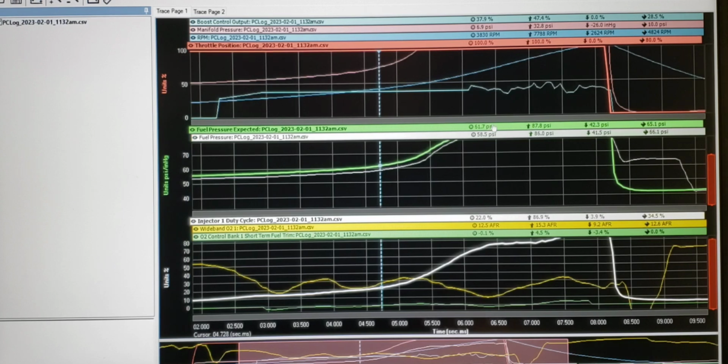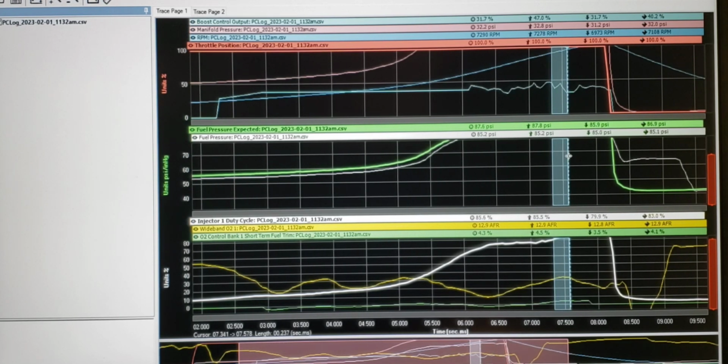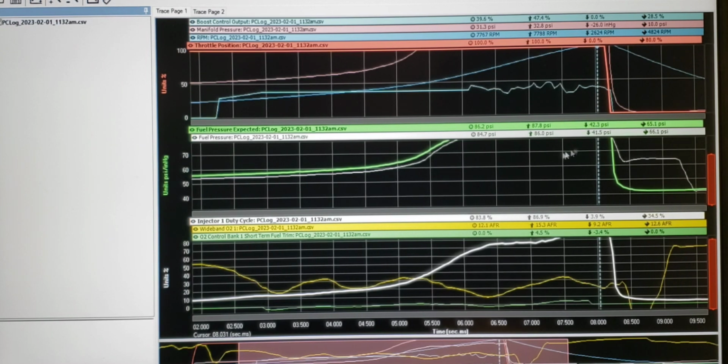and you can see our fuel pressure expected, our fuel pressure really close now as we move through here. Fuel pressure is 85.2, pretty solid. This is probably a sensor setup issue in the map, because what we see at base versus what we see once the regulator is working, because it is a really small Aeromotive, it doesn't really bypass enough, we get a little bit of pressure differential. Not necessarily that the car is out of fuel pump or anything like that, but I did also up the base pressure.